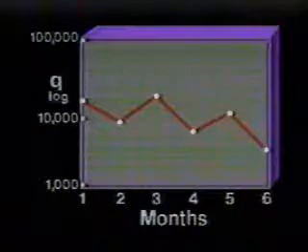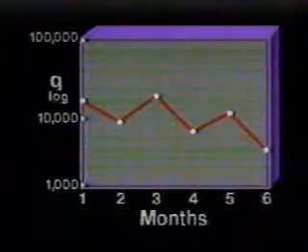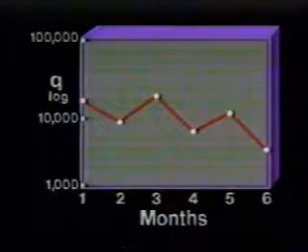In order to obtain a single straight line on semi-log paper that we expect for the rate-time curve, we have three choices. We may eyeball the data, that is, on a somewhat arbitrary basis, draw the best straight line that we see through the points. Although somewhat inaccurate, this procedure is often used. Alternatively, we may smooth the data by using a method of averages.